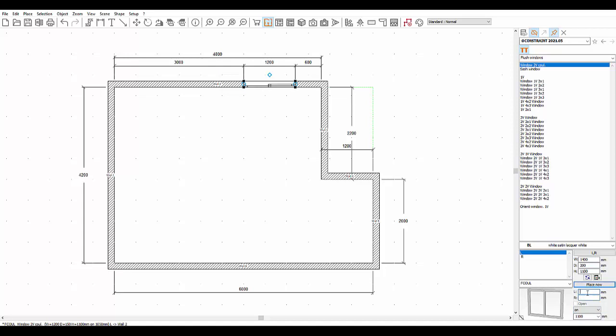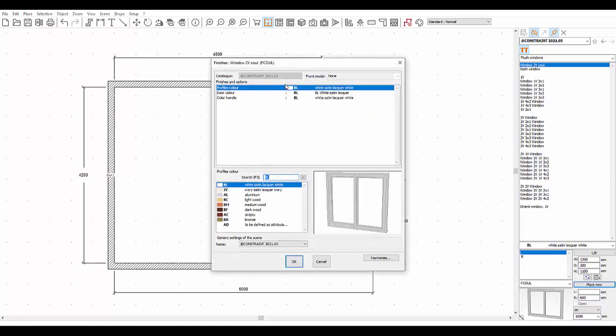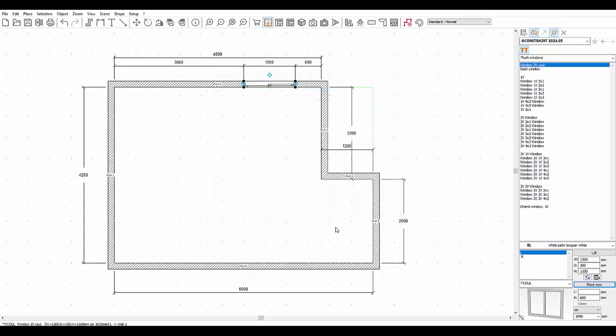Let's modify as follows: width to 1200 mm, placement altitude to 1050 mm, and positioning to 650 mm from the right. For the non-connected mode, it is indeed the image itself that you need to drag and drop into the wall, like this. The window that then opens lets you put in the finishing touches on your element. The placement of any and all other elements can thus be done in the same way.